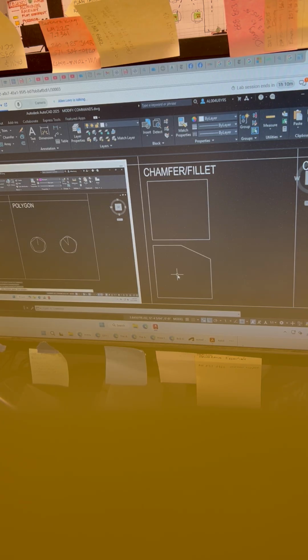All right. Now here's another thing I want to do, and then we'll finish up with trim and fillet and chamfer. I'm still in the command. If you need to, start the command back up again. I'm going to change the radius back to 6 inches. And I'm going to hit multiple here.